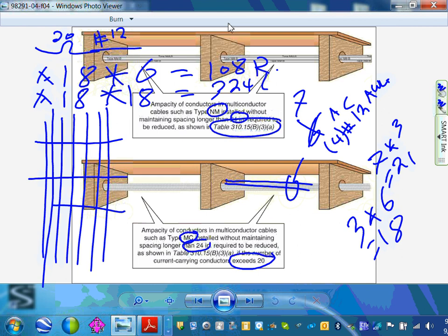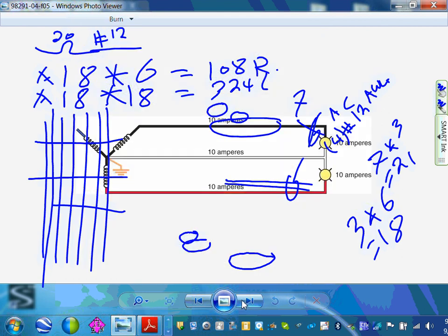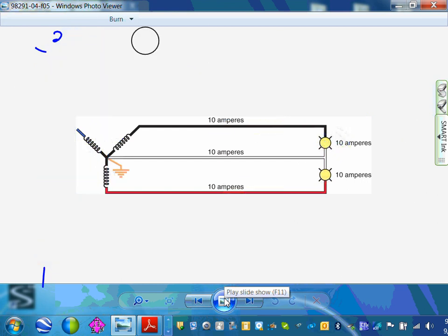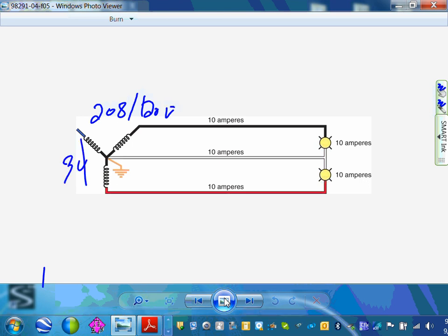So okay, but pay attention to the derating on these. A lot of circuits. For the neutral, this is just a few things about the neutral conductor. We're doing three-phase, so please, as you move with three-phase, this is typically a 208/120 volt three-phase system.